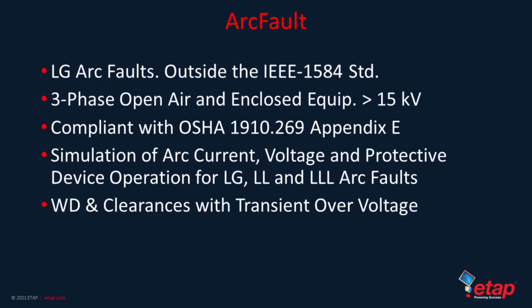ETAP's high voltage arc flash module is called ArcFault, and it provides the ability to do line to ground arc faults on locations that would be outside of the IEEE 1584 standard, so typically locations that are above 15 kV. It also provides the ability to do a three-phase open air and enclosed equipment, again above 15 kV, and it's compliant with OSHA 1910.269 Appendix E.